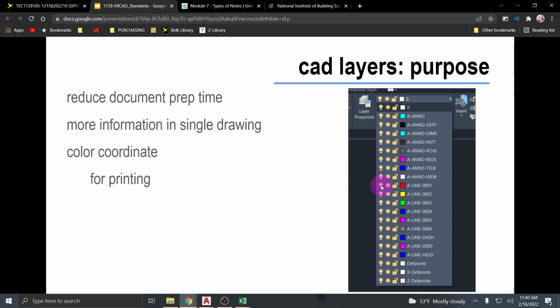So we can change different settings related to these layers. And in the software itself, we typically are also going to apply them different colors for two reasons. One, it makes it a little easier to look at a drawing and understand the different parts or pieces when everything's in different colors. And two, for something called color plotting.